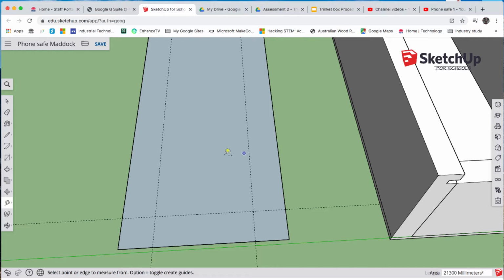Very good. Now I'm going to use a new tool, which is one of these arc tools here. I'm going to use a 2-point arc. So if I click here, it's this second one here that I want, 2-point arc. And I'm going to click across to this intersection here, click, click, click, click. There we go. We've now rounded the corner.